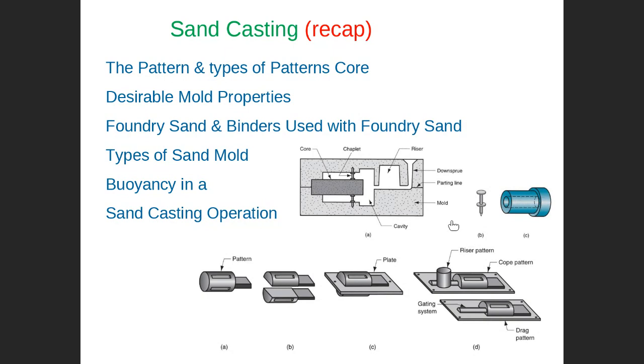And sand casting is made of sand mixed together with a binder material. We call it green sand, and we call it green sand because of the moisture inside. So it is sand combined or mixed with clay as a binder, maybe synthetic material, maybe natural material, some chemical additive, and then this will be ready and be used in the molding.